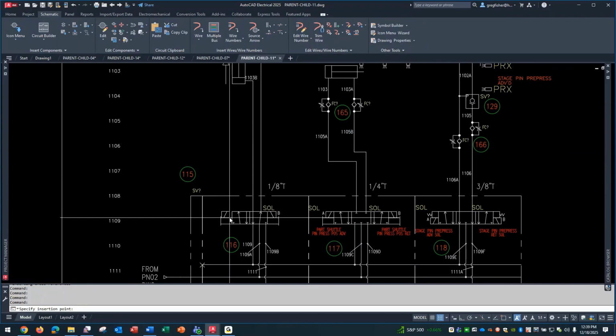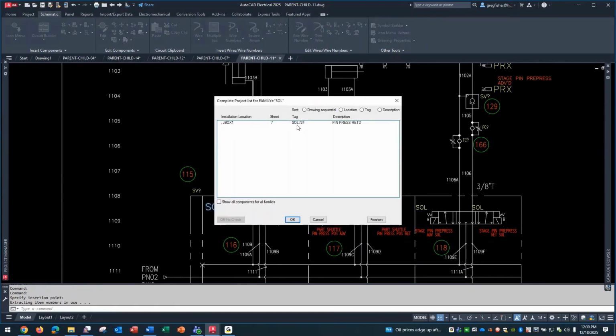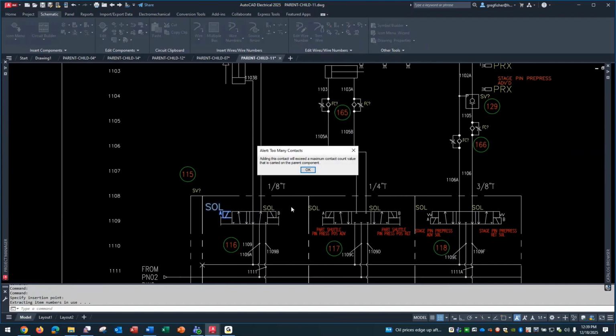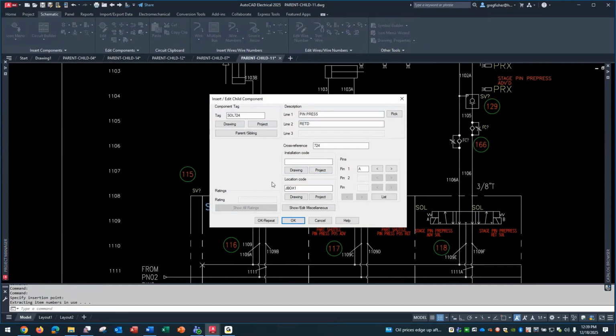In this, I'll drop down, let's say right here. And I'll pick that solenoid that I just dropped in. In this, I'm getting this because I added an extra 1 on the end of the symbol name. Normally I wouldn't. But it still works fine, carries all the information from the parent symbol. This actually does have a pin/terminal number on it.